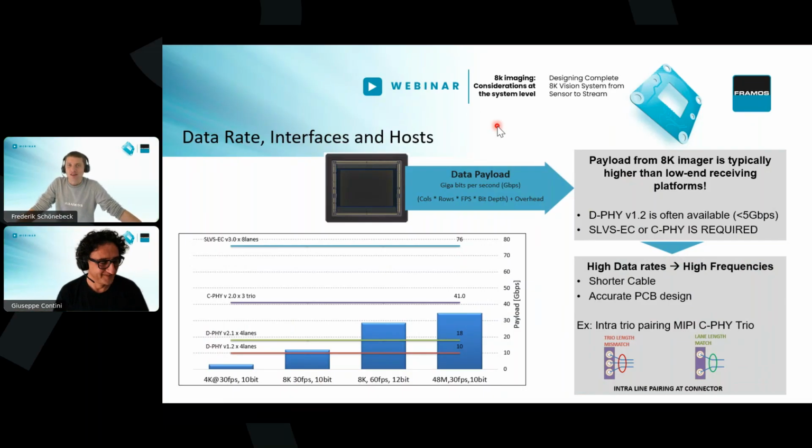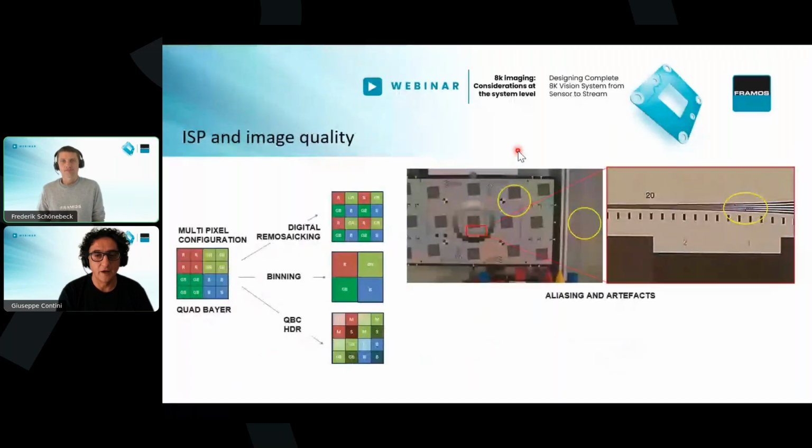There are a couple of questions on the optics. You mentioned in your presentation the 06A 1-inch sensor. How about the chief-ray angle for that sensor? Are there any exotic requirements on the lens that arise from chief-ray angle match? A good question indeed.